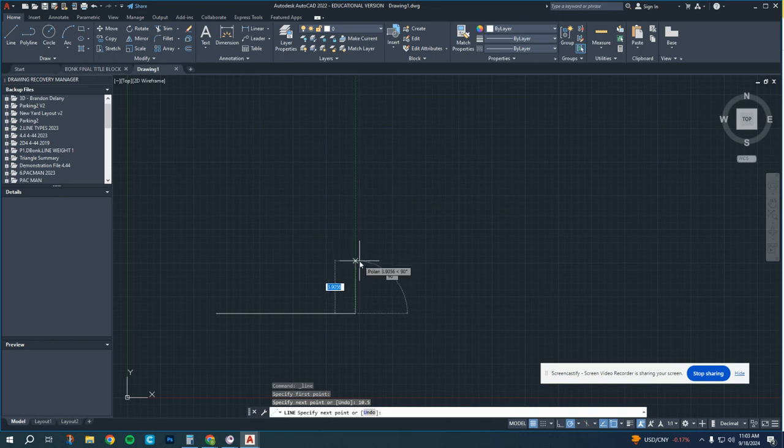and then continue on, allowing you to draw more lines. So we're now just going to finish out a box page border by going up, and it's going to be some given number. You type in the number 8, hit the enter key. It's going to make an 8-inch vertical line. Start going back to the left here from that 8-inch vertical line. You're going to go back 10.5.